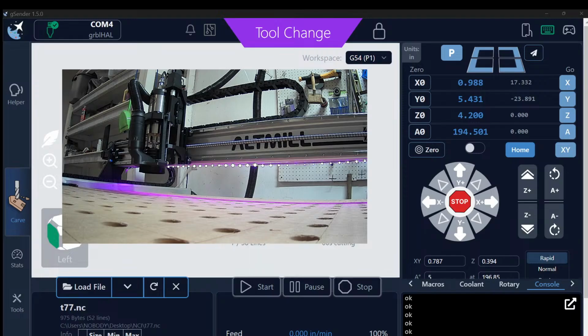You guys can be upset with me about being critical of this, but when you have this machine, you can't have these problems. You cannot have these problems. Again, I've been doing this 30 years. You know what I need? I need to type in what I want to see here. I want to type in G91, G28, Z0. I want to type in coordinates to go to. If I type them in wrong, it just errors out and I can't do anything. I type them in right. I don't need to hit cornering buttons when, if the machine's not homed, it's going to some random place.